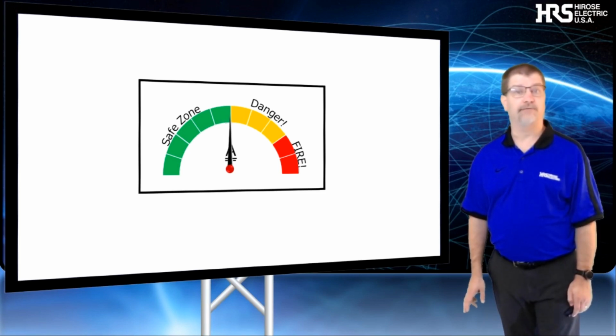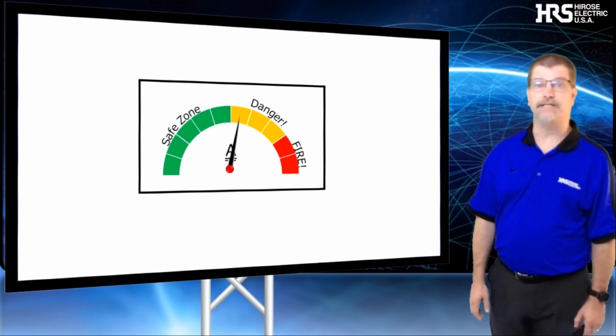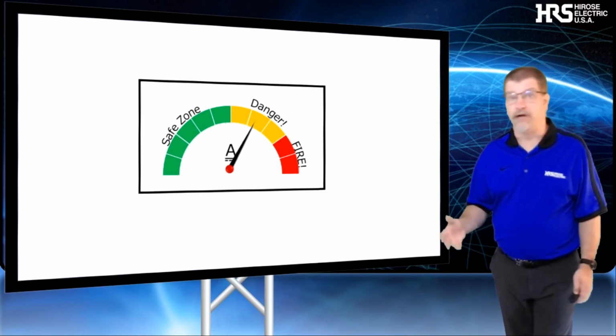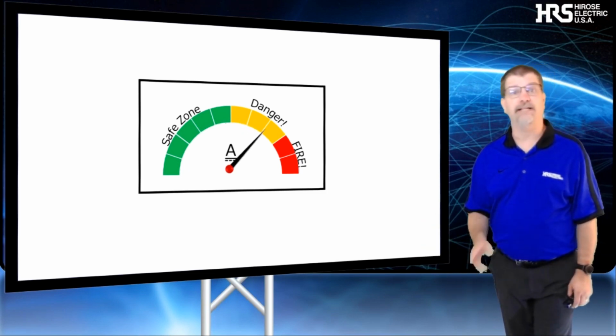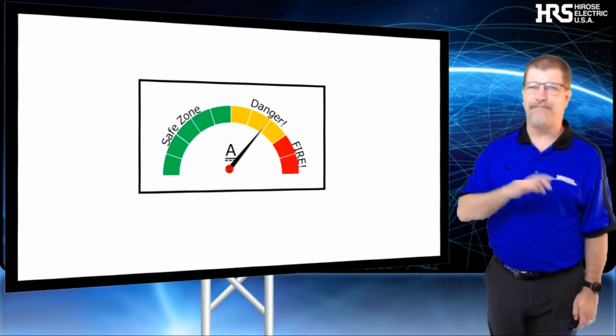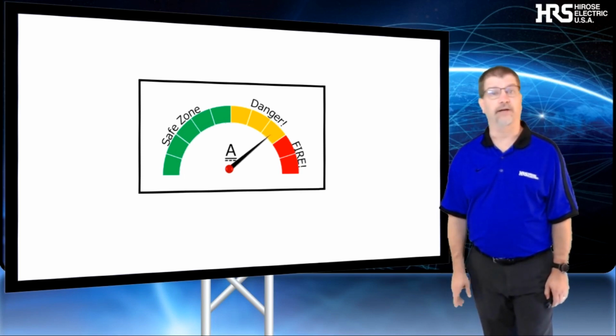How does this impact the rating, you ask? Well, the electrons will travel over the path of the least resistance. This means that contact A may be carrying 60% of the power in our example, 6 amps, and contact B may only be carrying 40% or 4 amps. Suddenly that 5 amp contact that you initially selected is being pushed too hard and overheating.